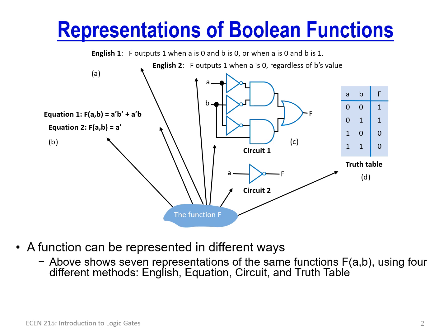And so you write down all those possibilities. You've got possibility 0, 0, 0, 1, 1, 0, and 1, 1. And of course, you evaluate the function in each one of these. So you can evaluate this function or this function. And since it is simply not A, or A prime, then we look at A. A is 0 here, so therefore F must be equal to 1. Here we have A is equal to 1, so therefore the output is 0. It's as simple as that.